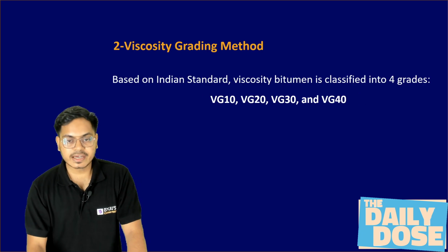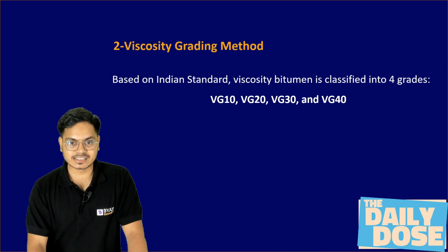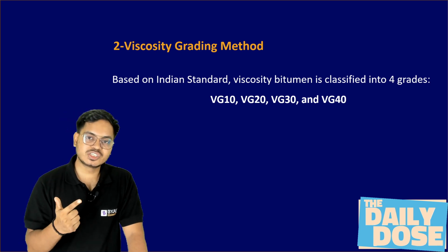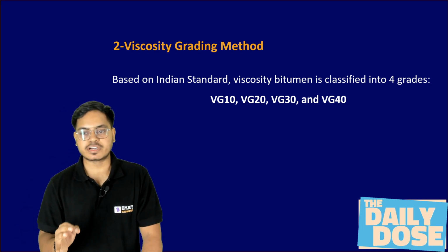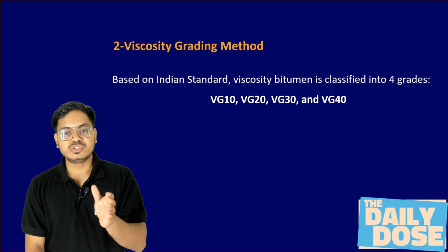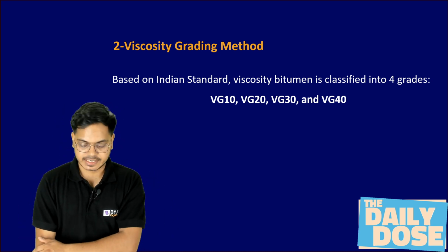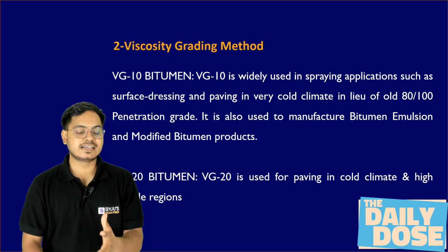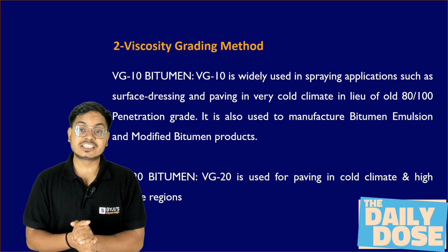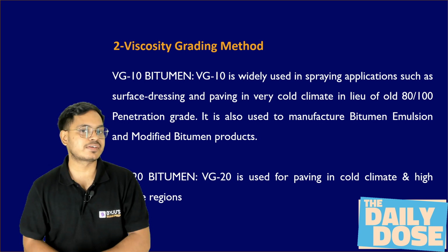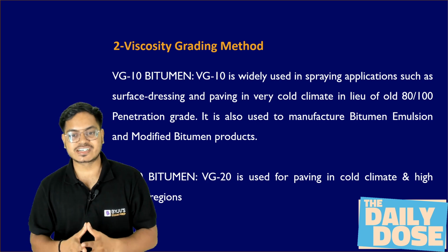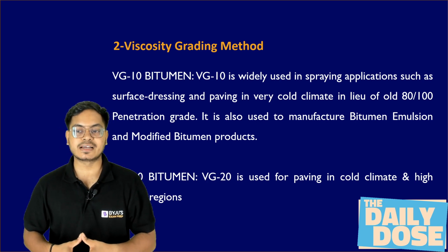Now we are using the viscosity grading system where we have 4 types of grades, which are VG10, VG20, VG30, VG40. Now, what is the usage of these viscosity grades? If I talk about VG10, it is widely used in spraying applications since it has the least value of viscosity, such as surface dressing, and paving in very cold climate, right?